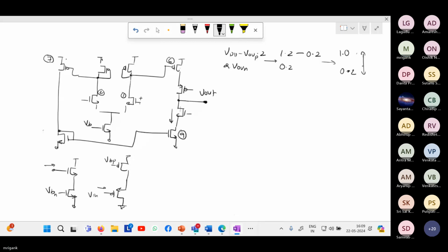Quickly, Nandita. If we have only the NMOS at the output stage, then if this is the voltage we apply at the gate, I know that the drain voltage of the NMOS should be greater than or equal to VG minus VT, right? If the gate is pretty high, it may push the drain voltage of the NMOS quite high, which may lead the PMOS above it going into the triode region. Anybody else?